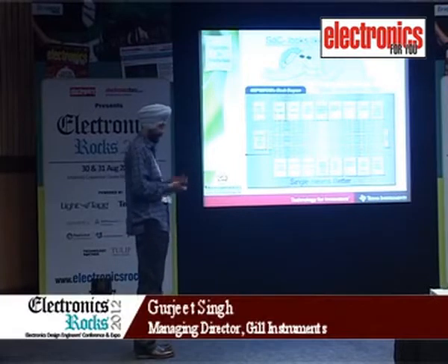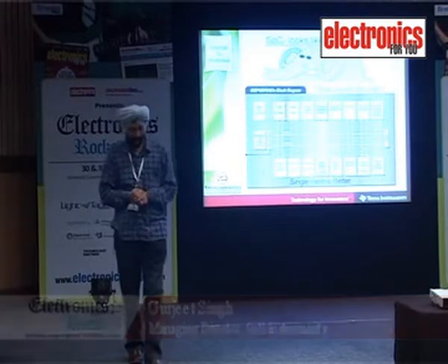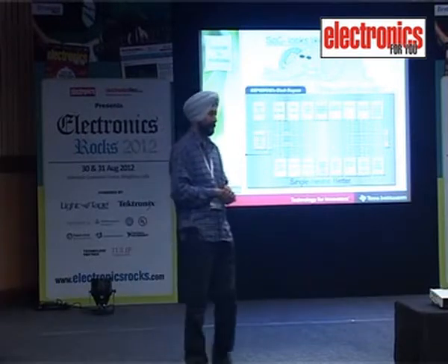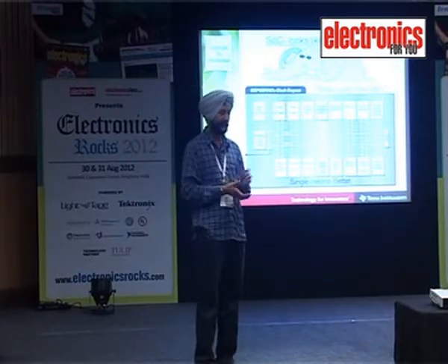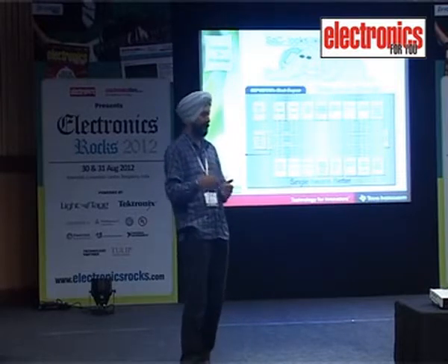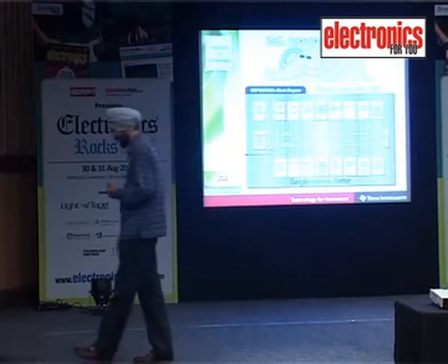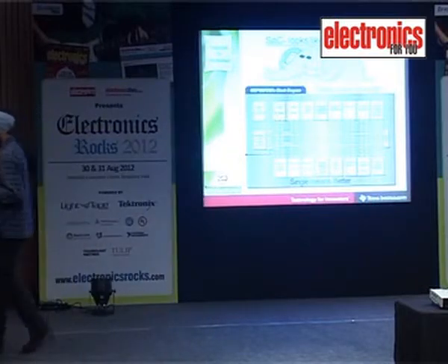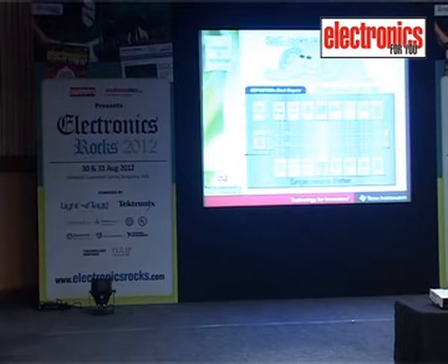And for fail-safe operations, you have a watchdog, which can be used as a watchdog timer, or it can be used as a purely watchdog, where it will take care of your software health. In case the system gets hanged, you will be able to reset the system. So this is how it looks, the complete SoC.